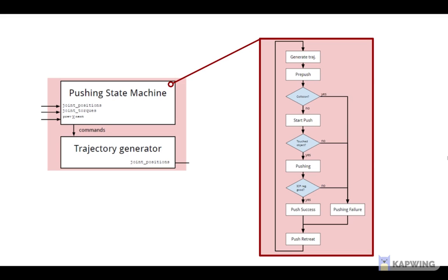To introduce these deliberate perturbations into the scene, a simple task-level controller to plan the pushing maneuvers is implemented as a state machine, which controls the trajectory generation and following behavior, accounting for both unexpected collisions, successful interactions with the target, and successful isolations of a single object. After a successful push, or when an unexpected collision or other failure might occur, we make sure to retract the arm away from the pushing target and get ready to repeat the entire process.